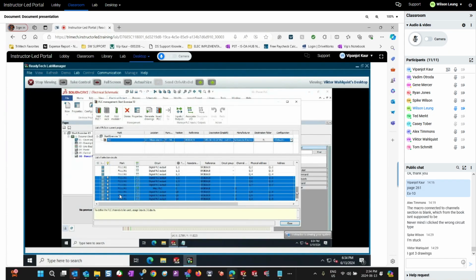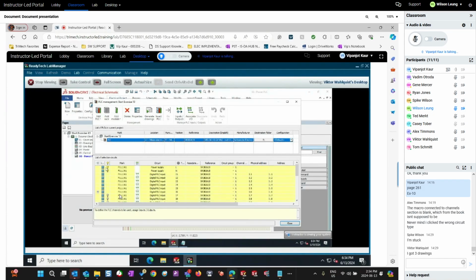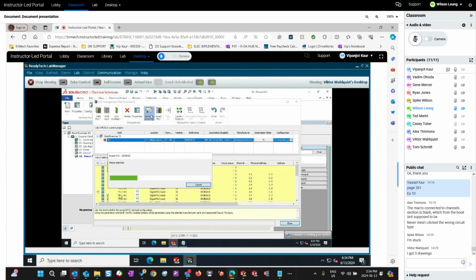Now click on generate drawing button. Make sure your right configuration is selected on the top line item. On the very first blue line, last column is configuration. Is that what you want? The default one? Pick the green one, please, if that's what you want. Now click generate drawing. You would only get 2 drawings now. Can you test that? Thank you.